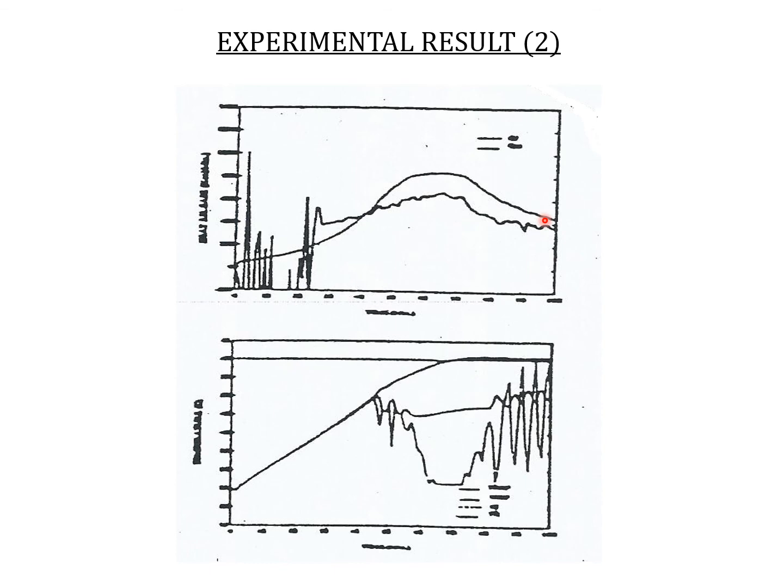The formulation is different, and this can also be called a modern method, because it's computer based. You need a computer to compute that. You can't do it by hand, cannot do it on paper. Of course, you have to connect it to the DDC, directly to the computer. Once the measurements come in, it measures, calculates, then it comes up with a manipulated variable. And that's typical of modern methods of advanced control, which need to be computer based.